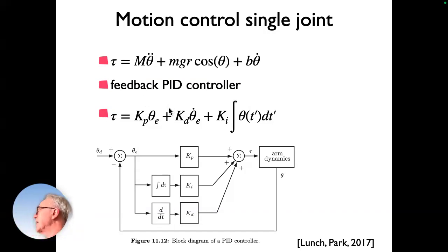And so this is the classical PID controller. I think all of you might have heard about it, where you're essentially saying, I put in nothing if I'm already at the desired state. So my desired theta is exactly what I actually have as theta, and then my error signal is zero and I'm not sending anything. The deviation from that is this error, and that is a proportional term.